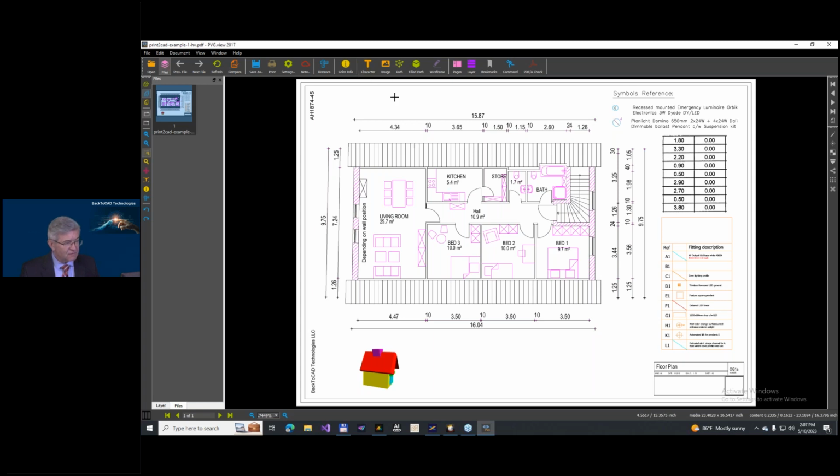So here on the screen, you can separate the only 4 possible PDF entities. You see, a PDF file is not a CAD file. In a PDF file, you can define only 4 entities, 4 elements: text, native text, first element, then polyline, then raster image, and then boundary edge. Only 4. And you can separate them here.